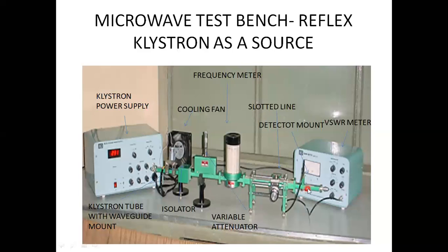This crystal will convert the microwave energy into electrical energy, and then it will be given to the VSWR meter. And this VSWR meter will measure how much voltage is flowing in the waveguide. Okay, so this is the basic setup of a microwave test bench.